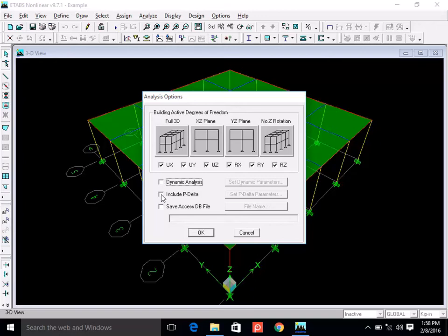This is generally where you have either lateral loading or bending moment on your column, which is generally the case all the time. For example, if this column has only axial force, no eccentricity, then you can design it as an axial column. But if this column has bending moment as well, it will bend like this. So load is here and the column has bent due to bending moment. Then the column has eccentricity with respect to the vertical line. The vertical line is here, but when the column has bent, an eccentricity is created right here in the middle.